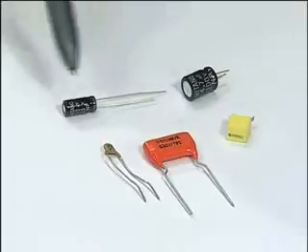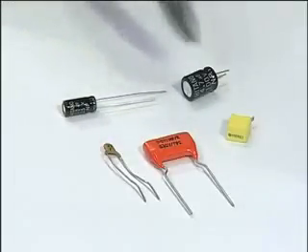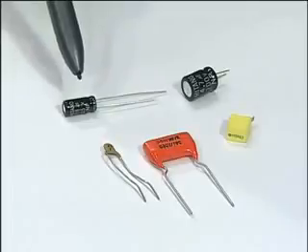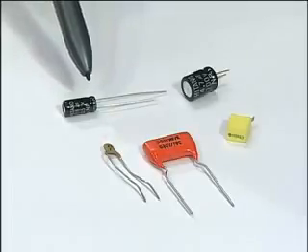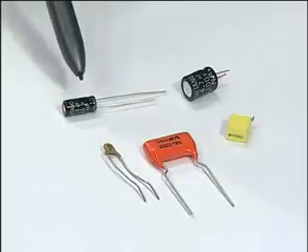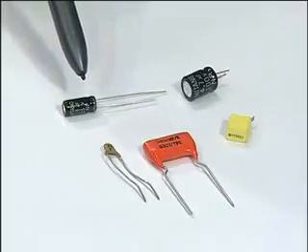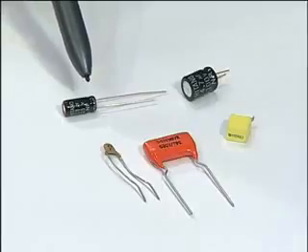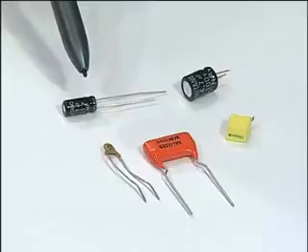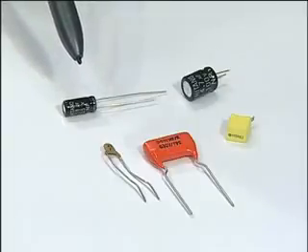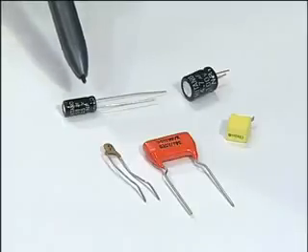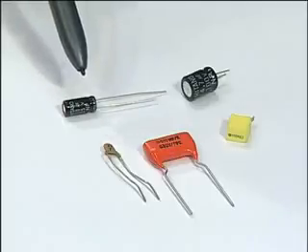Now, these two black capacitors that you see, they are polarized. They are what you call the electrolytic capacitors, and specifically here I have aluminum electrolytic capacitors. They are very frequently used in power supplies for holding the charges. They can hold large quantities of charges, and they can come in very large capacities.